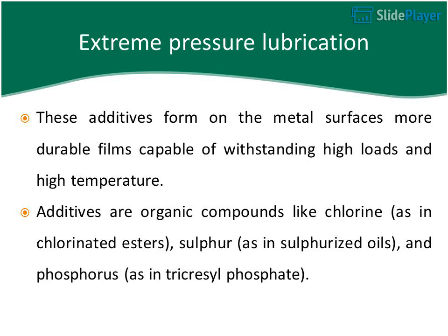Extreme pressure lubrication. These additives form on the metal surfaces more durable films capable of withstanding high load and high temperature. Additives are organic compounds containing chlorine, as in chlorinated esters, sulfur, as in sulfurized oils, and phosphorus, as in tricresyl phosphate.